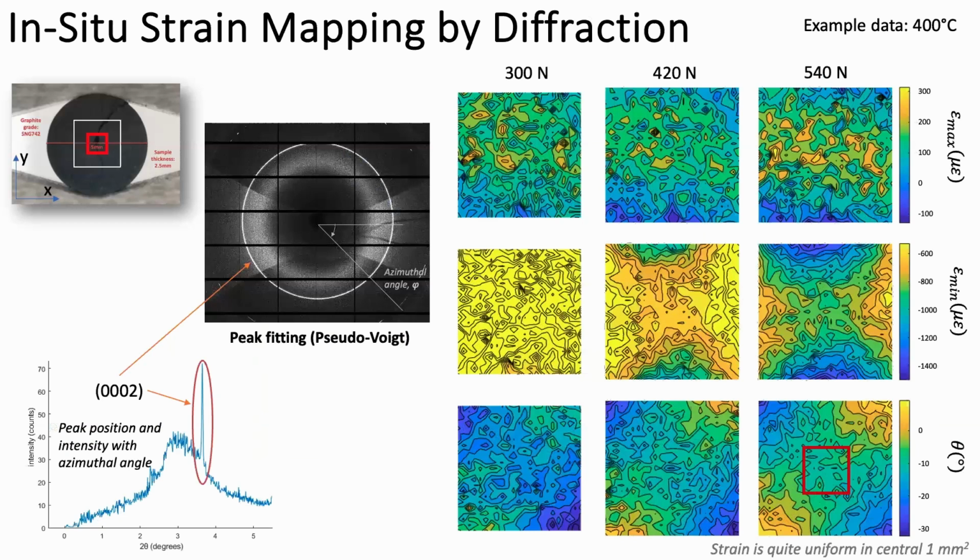And then if we go to the next slide, the diffraction, we can map, again, the strains in the horizontal direction, the strains in the vertical direction, and the shear strains going around the ring and identifying the principal strains, which actually turns out to be very well aligned with the loading we get. And the sharp eyes will notice that, yes, we can see the compression in the vertical direction. There's not much happening in tension, which is not surprising because we're compressing the sample, it's splitting, getting fracture, and when fracture, of course, occurs, you can't sustain much tensile loads. So this is telling us and allowing us to see the effect of cracking in the sample.